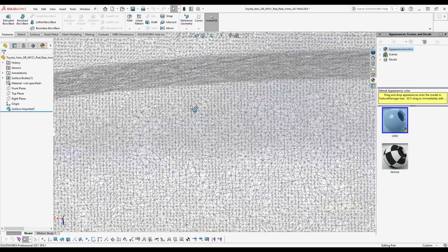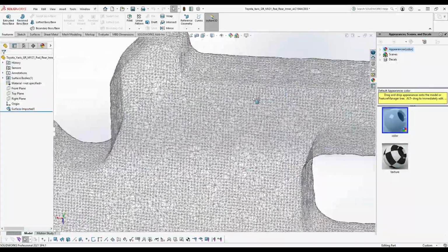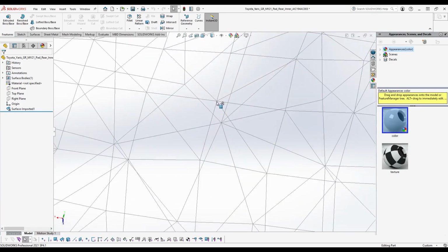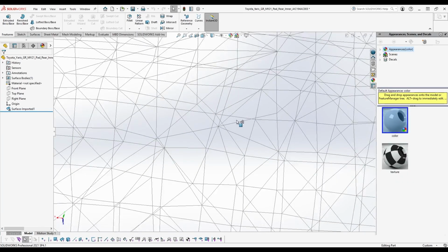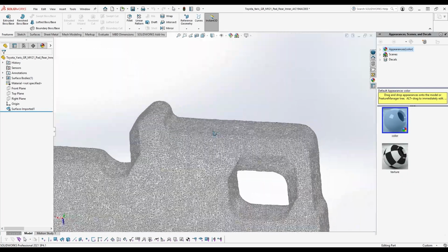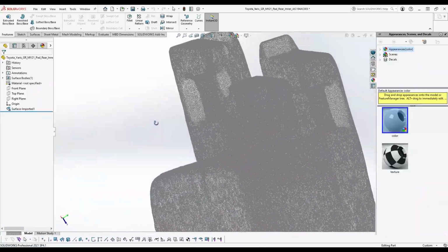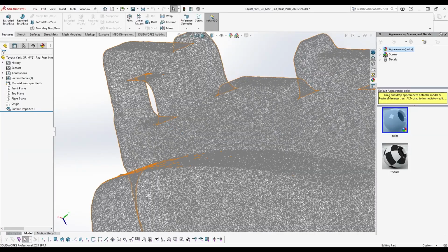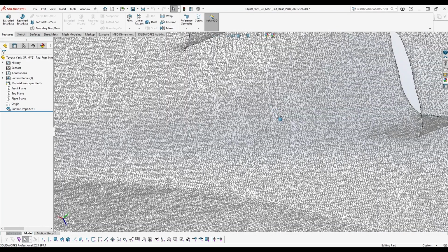And this is kind of what it looks like. You see it's like a little net here. Now, each of the actual points, the bit where the lines intersect, is the point. And these points effectively form the surface of the part that's been scanned. It's kind of hard to see with the resolution, but you get the idea. This is known as a point cloud. That's the important part, the most accurate part, because each of these dots has an accuracy in the virtual space of about 0.04 millimeters or under.